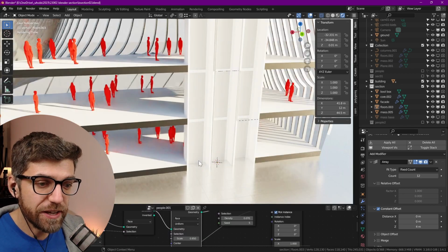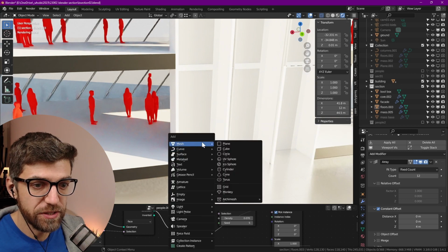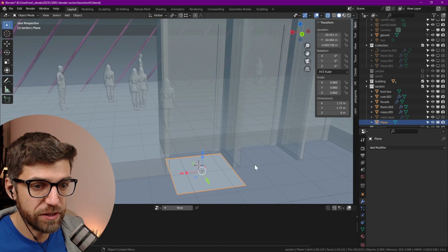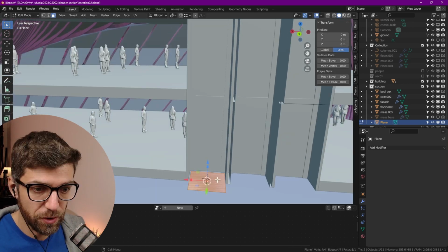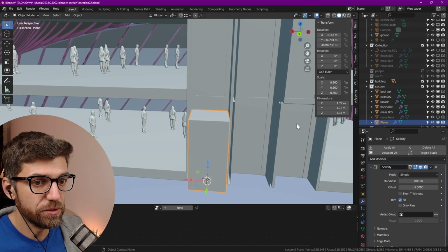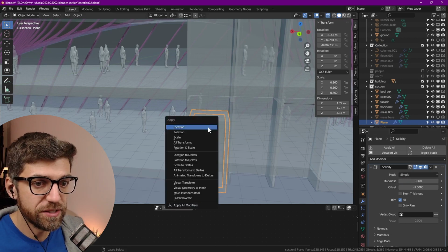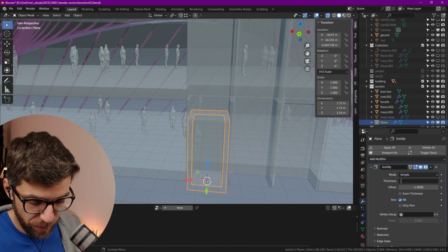As a last graphical bit that I like to add is some very simple lifts in there. So it starts with the plane. I'll shrink that down a little bit. In fact, let's go to regular solid view, to something like this. Go into edit mode. We'll extrude it. Select everything. And we'll add a solidify modifier to a thickness of 0.3. Now I want to apply the scale. So that 0.3 is true. And maybe that should be 0.2.